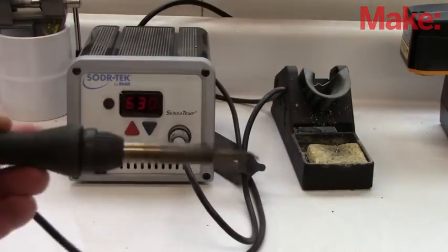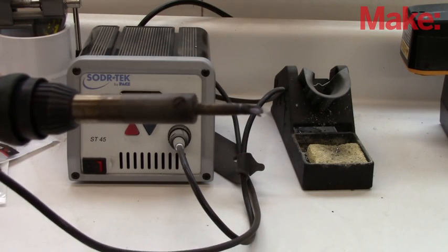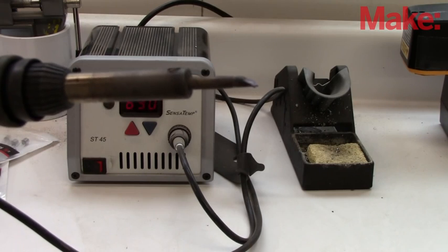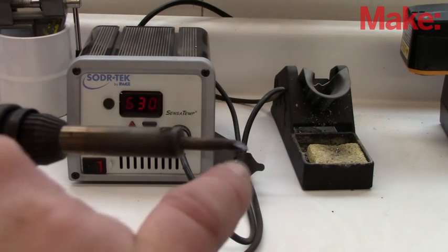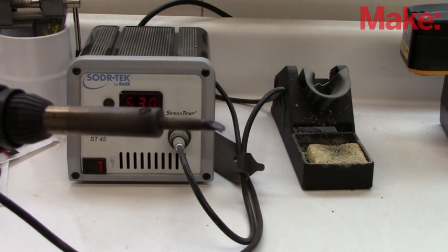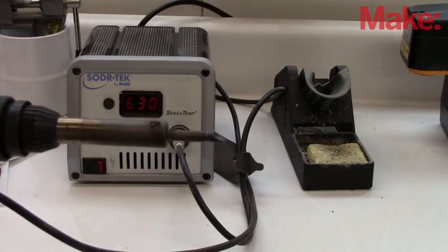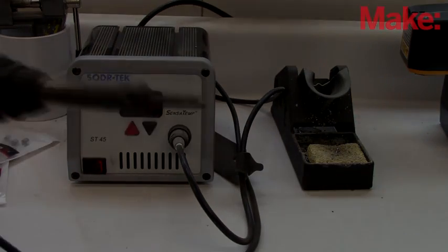The tips that I use can vary. This one is actually called a mini wave soldering tip. It has a little concave point at the tip, which actually makes it extremely good at doing surface mount soldering. More and more components are going surface mount nowadays, so it's good to have this tip, or at least a very sharp tip, to work in the surface mount area.